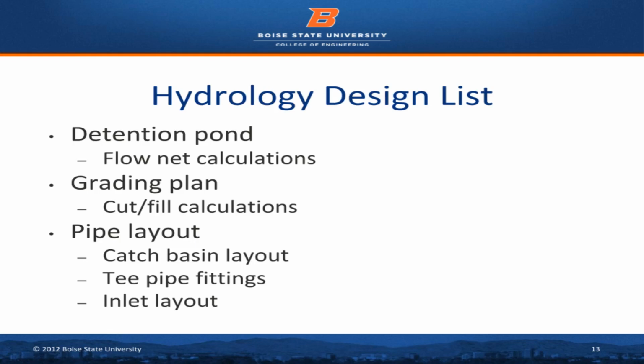So the 100-year flood is an expected event that is basically the furthest, most extreme catastrophe you would expect for this site. So we're designing with a factor of safety to contain all the water on the site, so that we don't have flooding going off or going into the road or anything like that.